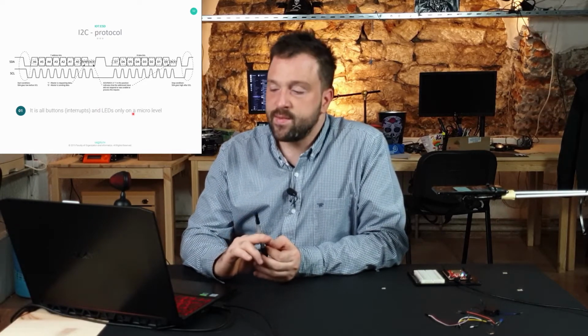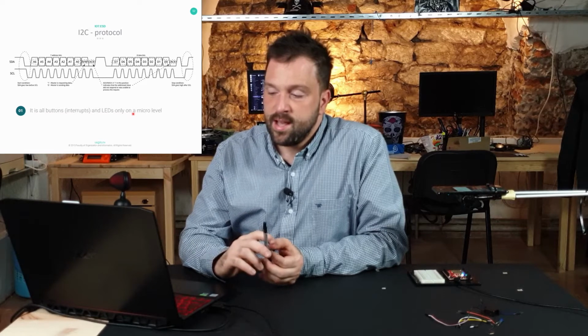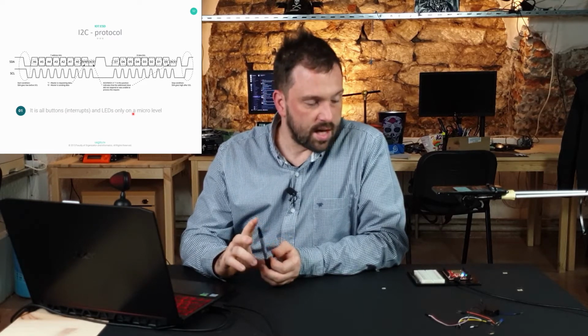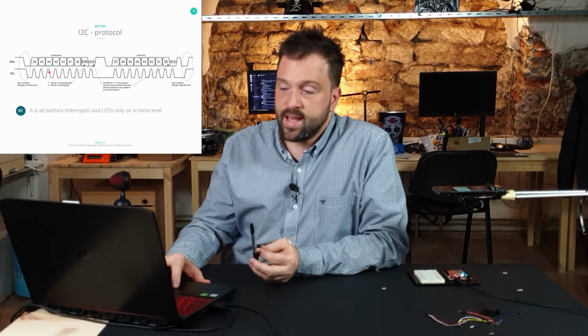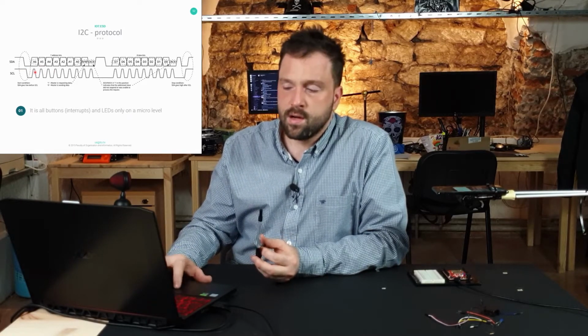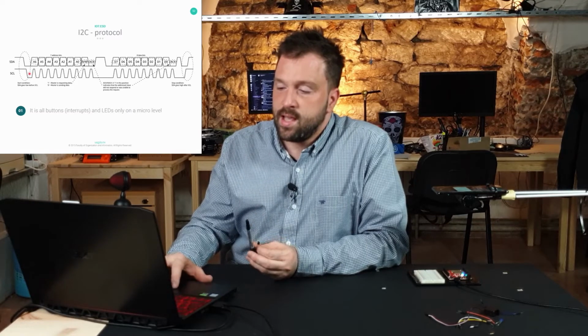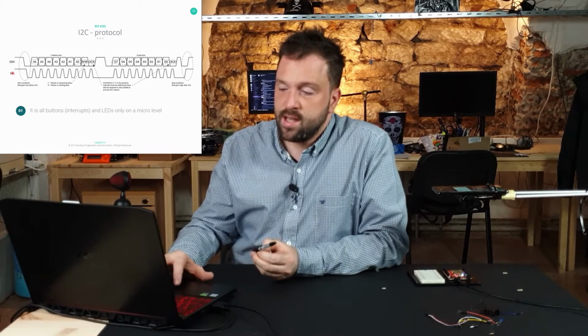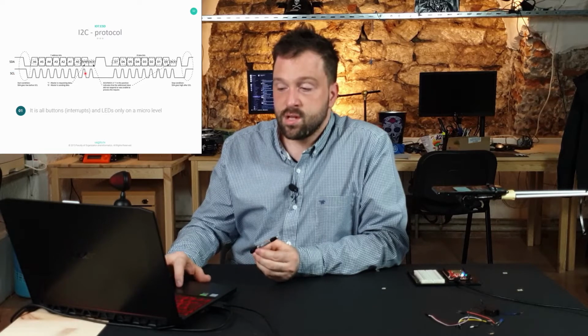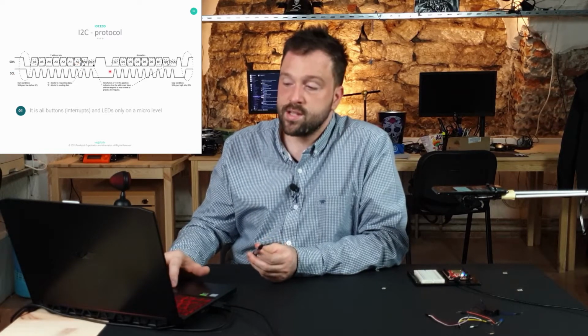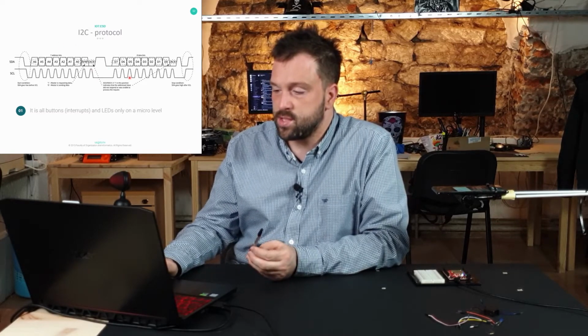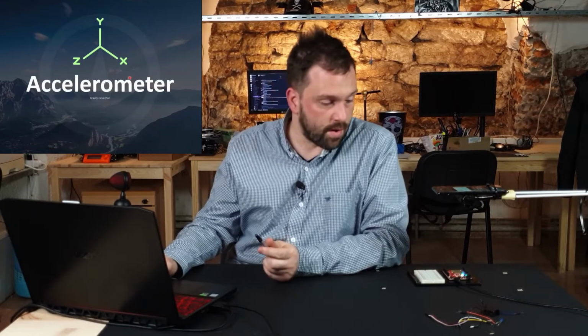Well, if you remember, we had a video on interrupts. We attached a single wire to an interrupt, which is the case here. If you attach, and this is obviously implemented like this sometimes, if you attach an interrupt on the SCL, you will get an interrupt each time the clock rises, and then you will do the reading and writing and so on. You can actually write your own implementation of the I2C protocol using just interrupts, as mentioned before.